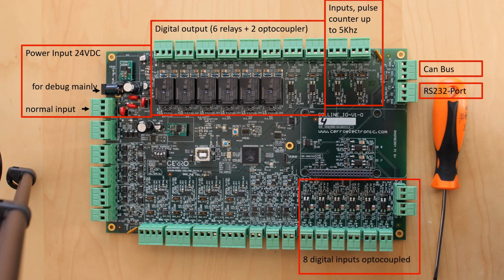Here we have the digital inputs, which are optocoupled. We have the area for analog outputs. This output can be in current or in voltage. We can configure it with these micro switches on the board. This is the area for analog input. Also, as before, we can configure current input or voltage input with micro switches on the board.